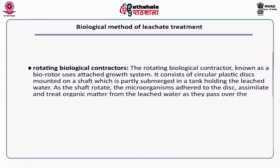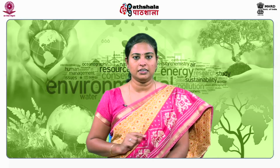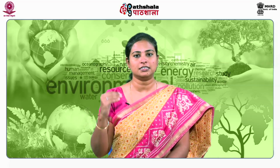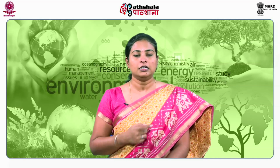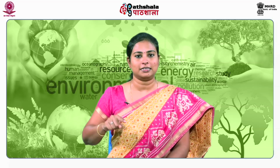The second unit that is popularly used for leachate treatment is the rotating biological contactor. Rotating biological contactors, also called biorotors, use an attached growth system. In this, you have a circular wheel or disc made of plastic, mounted on a shaft. Half of the disc is submerged in a tank holding the leachate. The shaft keeps rotating and the microorganisms start attaching themselves onto the plastic disc.